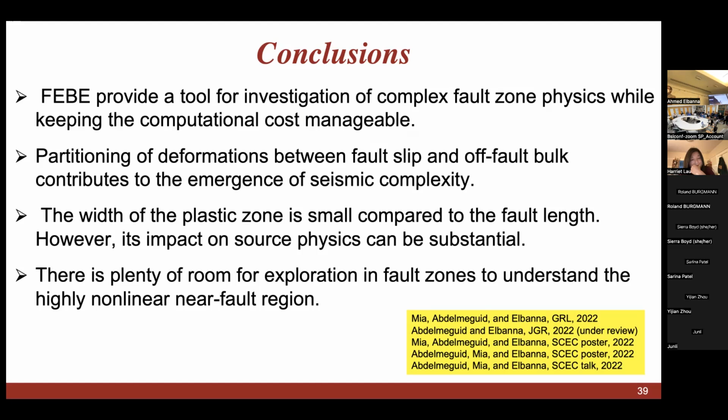As the accumulation of the plastic strain increases, is there a threshold, like at this point it will actually slip along this strain? Anything here, you could always think about as plastic strain. If you integrate the plastic strain in these two-dimensional models over the area, they give you some sort of plastic displacement or slip, right? But the difference here is that they are not localizing into a single surface. So you could think about that more or less like a shear band, right? The plastic strain that we are recording would definitely tell us that this side of the shear band is moving against this side by that much.